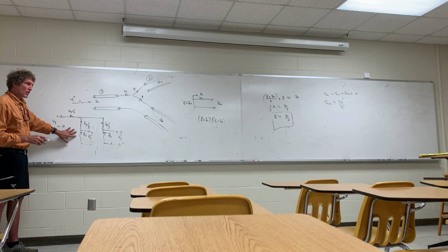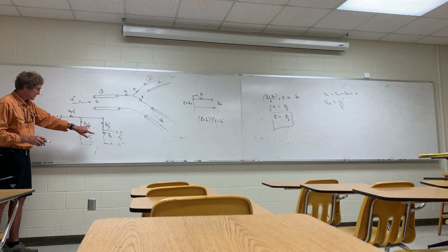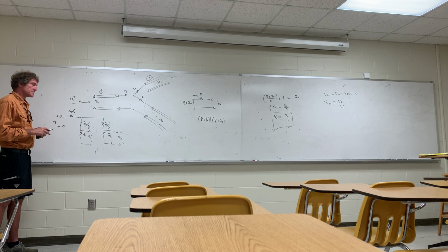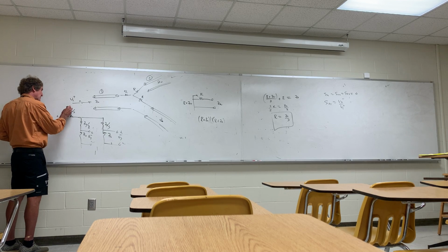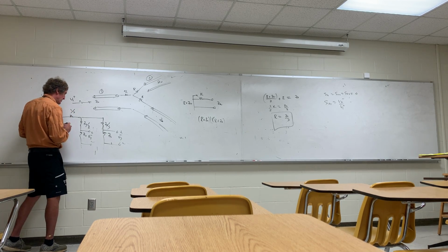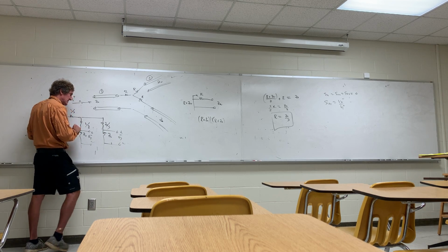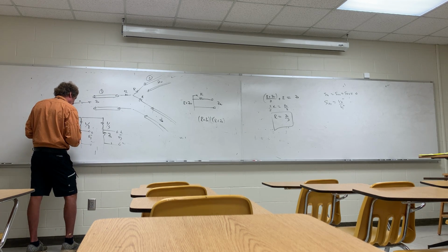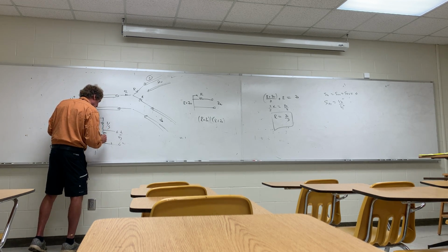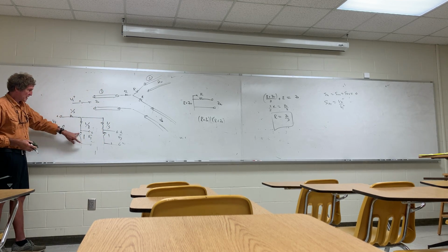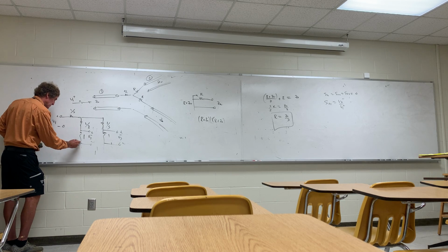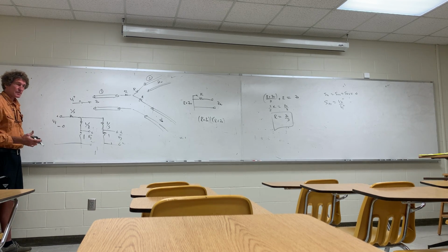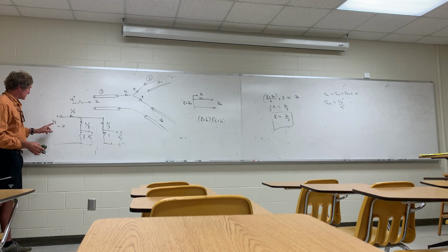So if I want the value of either V2 minus or V3 minus, how would you go about getting it? And by the way, the value of Z naught is inconsequential, so I could make this just 1/3 of an ohm, make this 1/3 of an ohm, make this 1/3, doesn't matter what Z naught is. Make this 1 ohm, make this 1 ohm. So how do you get the voltage here, V2 minus or V3 minus? Y'all see it's a simple voltage divider? I want to know what these two voltages will be with respect to V1.